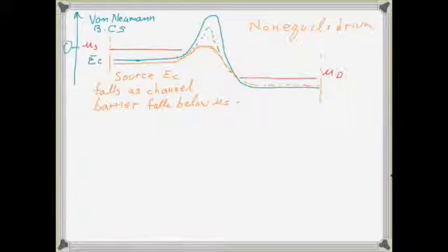You really can't think physically. You really have to think in terms of the algorithms that are being solved to do this. The first thing to keep in mind is that mu s is fixed. Your conduction band edge has fallen, so you would think the charge density must be increasing. And yet Poisson's equation is giving you a solution of charge neutrality in the leads.